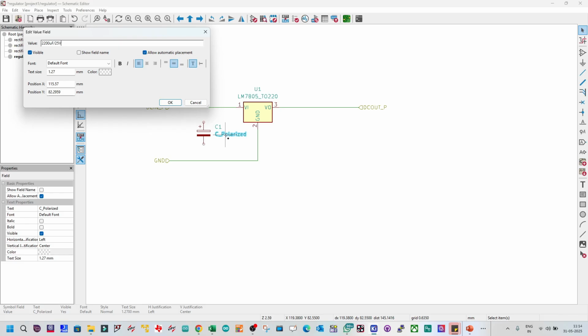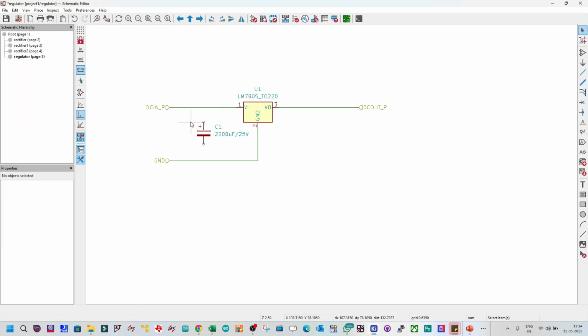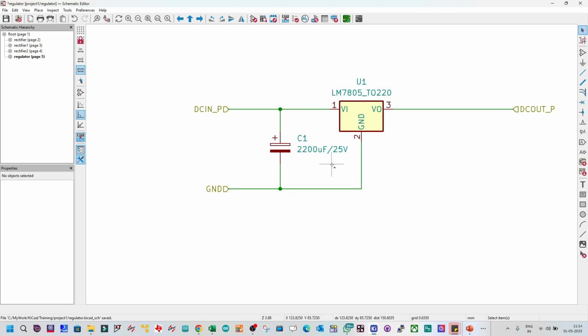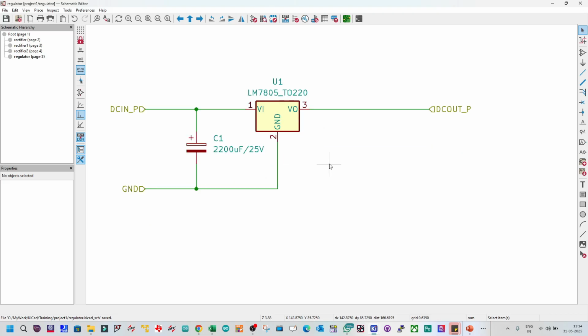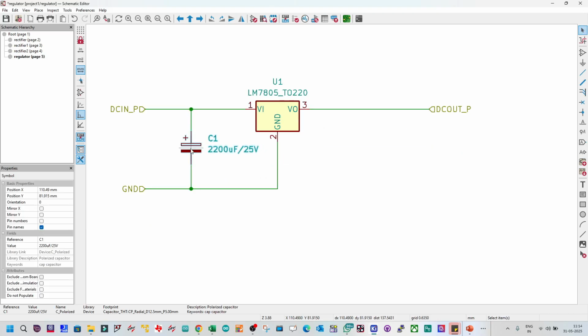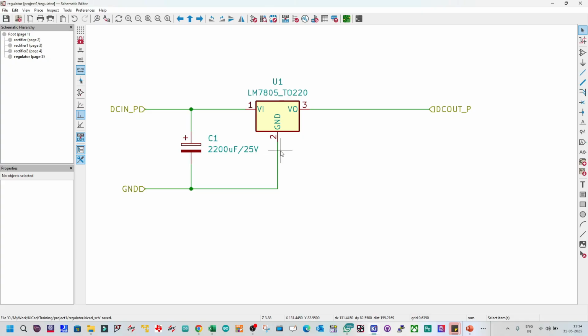25 volt, 35 volt. Yeah, 25 volt actually. Sure. So this is also very important. If you put in an unexpected value, your output won't be stable. It might oscillate. So C in and C out have some spec. I think we can cover that in some hardware design part later. But for now, just to get going, let us go ahead with this.